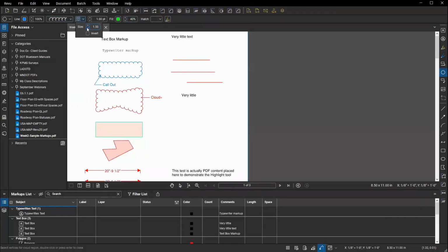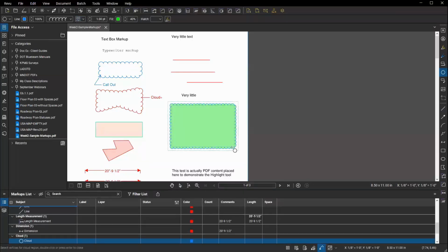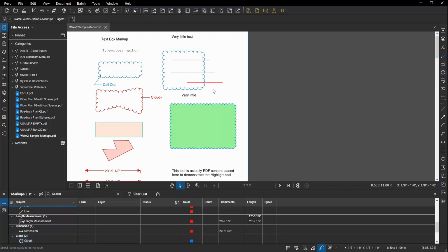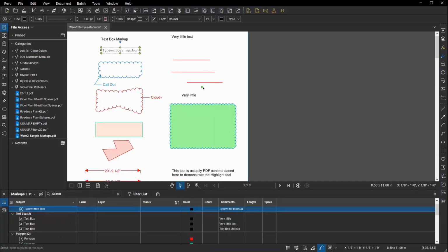So I'm going to drop it down a little bit. And now when I place a cloud, it's got the characteristics or the properties that I desire more so than what my default was. But here's the problem. It doesn't remember that. It doesn't know that I prefer that. So every time I go do something else and then I come back to place a new cloud, it reverts back to what it was previously. Now that can be avoided by modifying your default.